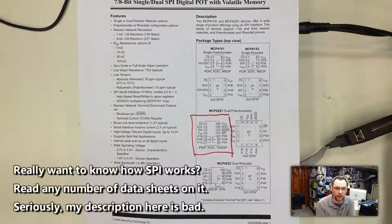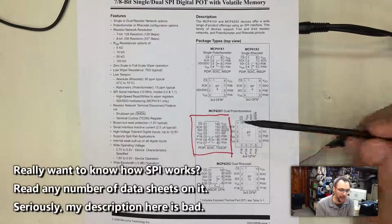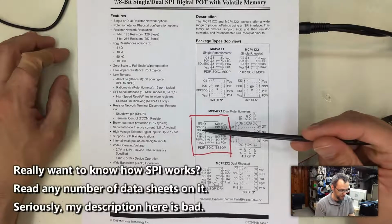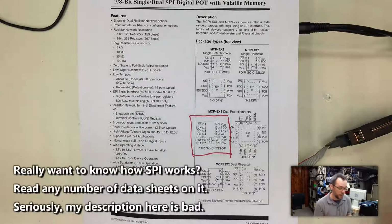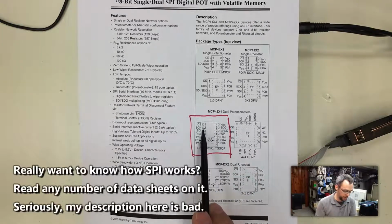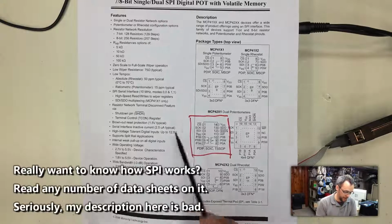Now, this is how SPI works. Basically, you assert the data bit, whether it's a 1 or 0, that you want on your data pin, then you clock the clock high and then low, or low and then high, depending on which SPI mode you're in. And for each one of those clocks, it basically ingests that bit. You clock that bit in, you change the bit on your data, clock another bit in, change the bit on your data, clock another bit in. So you just go ding, ding, ding, ding. You just poke it. And that's how you program it.